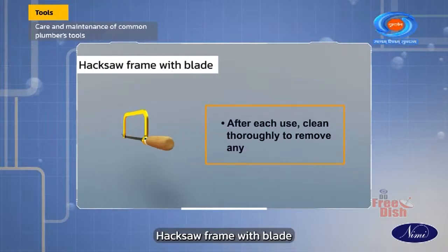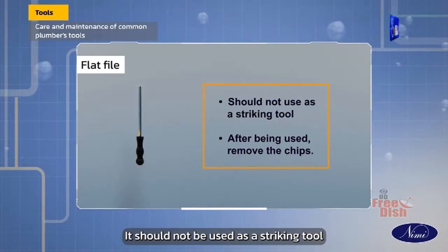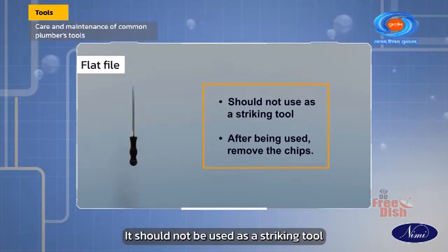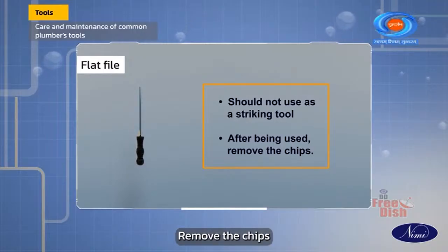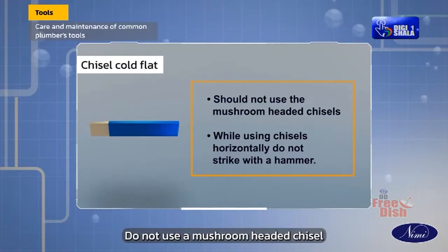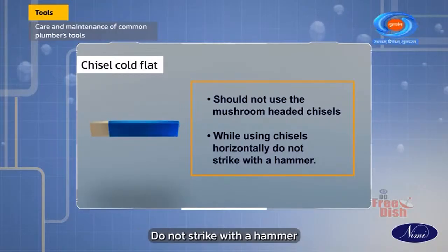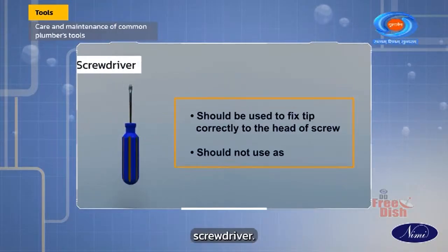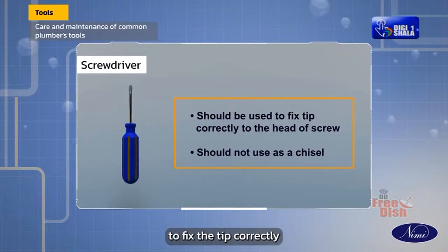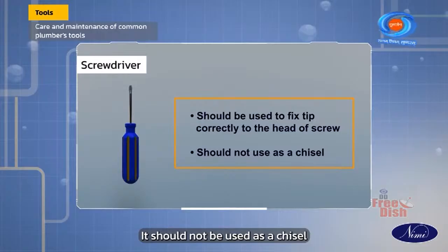Hacksaw frame with blade. After each use, clean thoroughly to remove any debris. Flat file. It should not be used as a striking tool. After being used, remove the chips. Chisel cold flat. Do not use a mushroom-headed chisel. While using chisels horizontally, do not strike with a hammer. Screwdriver. It should be used to fix the tip correctly to the head of the screw. It should not be used as a chisel.